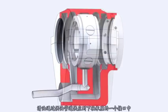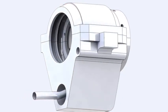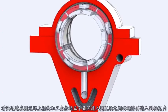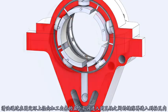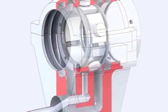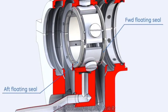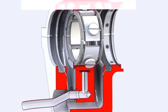For lubrication, oil is supplied through the oil feed pipe to a port in the lower bearing housing, where oil fills an annular space around the liner retaining ring. Oil is admitted inside the liner through 5 orifice holes, machined radially on the retainer ring to the gaps between pads. 2 floating ring seals are mounted on both ends of the retainer ring to maintain an adequate amount of oil inside the liner assembly.